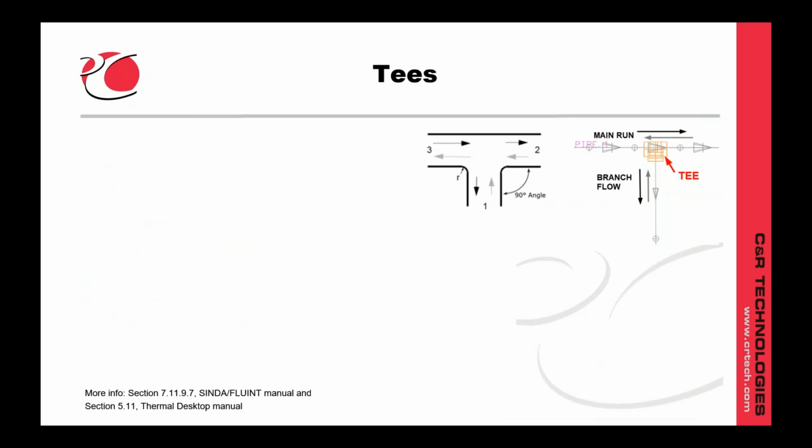We've added another modeling object called a T. This is used to provide a user-friendly method to model Ys and Ts associated with merging and diverging flow or in manifolds. FloCAD has no knowledge whether or not intersecting flow passages represent branched or diverging flow, despite what might be obvious to a user based on the graphical depiction of the drawing.